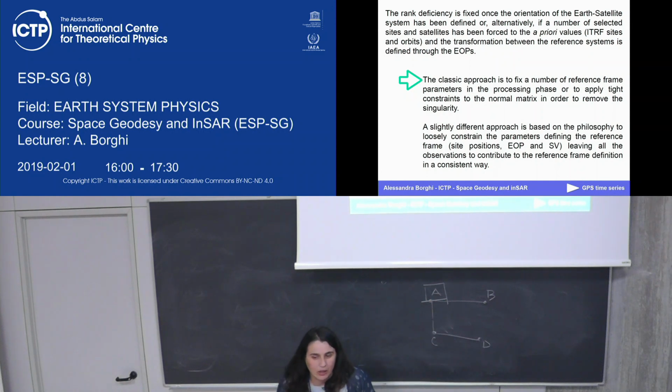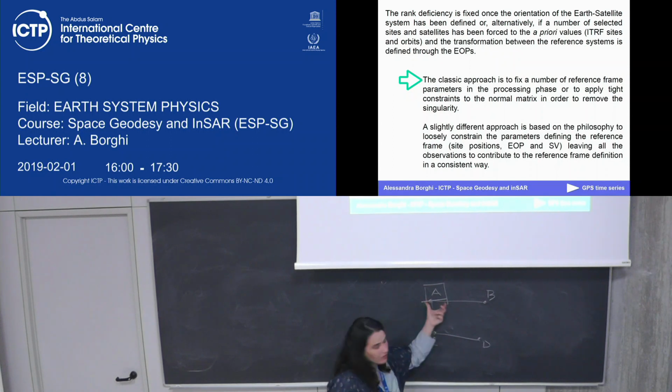For instance, the coordinates of a reference point. So in your network, in a geophysical application, but also in surveying application, you introduce in your network also some reference points. For instance, stations from the ITRF network, or for the upgrading in your country, because ITRF is global, but in your country you can have more stations that are framed in the ITRF, and you can use these.